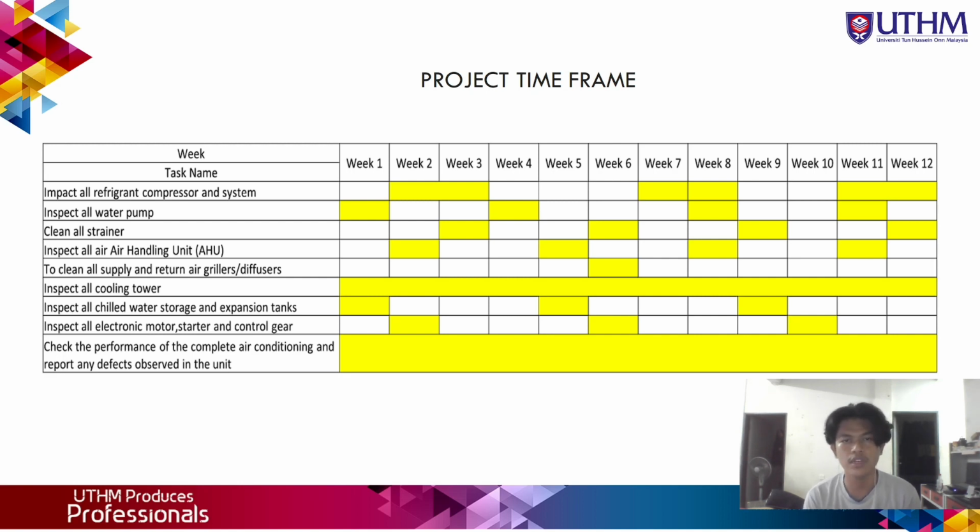We don't do that in every week. Inspect all water pumps. We will do it in week 1, week 4, 8 and 11. Clear all strainers. We need to clear the strainers in week 3, week 6, week 9 and 12. Inspect all air handling units, AHU. We can do it in week 2, week 5, week 8, week 11.